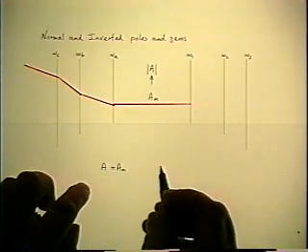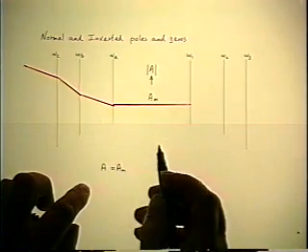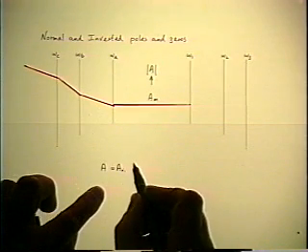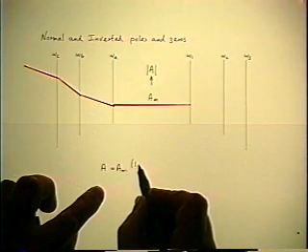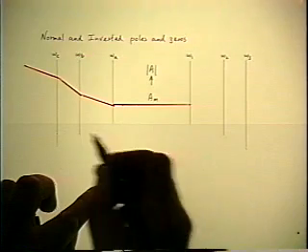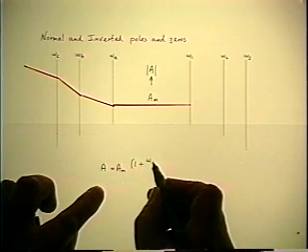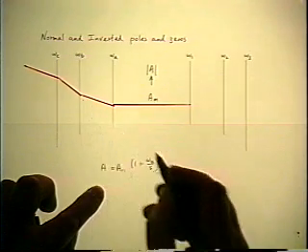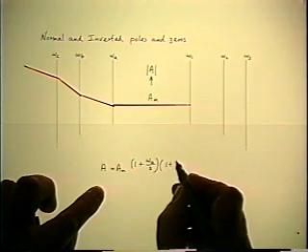Okay, let's look at that. Just ask those two questions sequentially. If you look down from AM, you see a concave upwards corner, so it must be a numerator factor, but you're going down in frequency, so it's an inverted zero at omega A. Omega B is the same thing again.